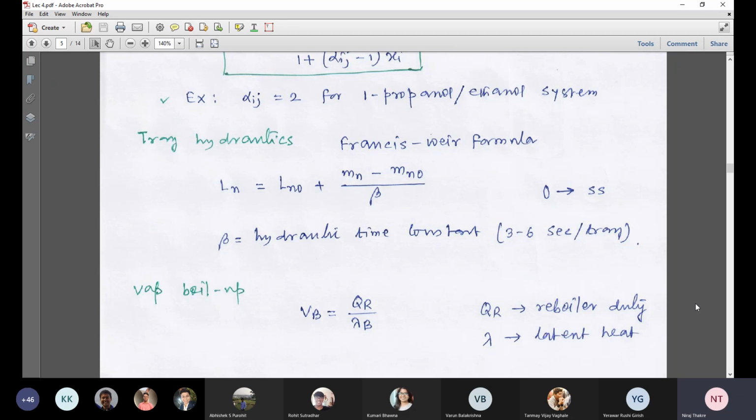What you told, that is also somewhat correct. That is a function of temperature. So if you see the final form of the Clapeyron equation, lambda is basically a function of temperature and two Antoine constants B and C. One student told an empirical equation. So the answer is the Clapeyron equation, using which we can calculate this lambda B for a mixture, if we do not want to consider the constant value of lambda for component A and component B.